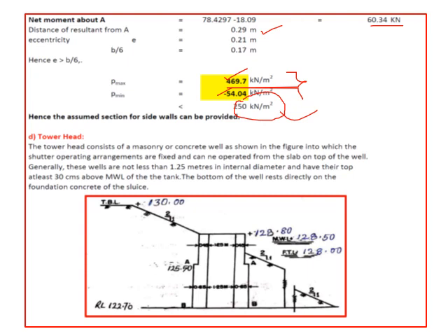And then, if the top of the bund is very near, steps can be provided here, and a person can come here and regulate the gates. Otherwise, if it is a little far off, then you can extend this to the top and provide a footbridge somewhere here like this. So a footbridge can be provided and this can be extended up to the top. A person can come here and regulate. So this wall has to be extended right up to the top of the bund. But if it is very near to the bund, steps can be provided, and the operating person can come here and regulate the gate.